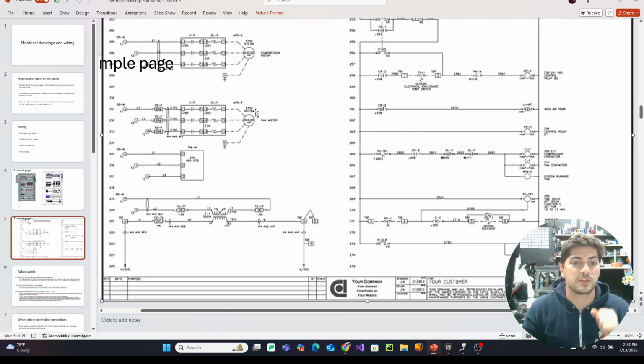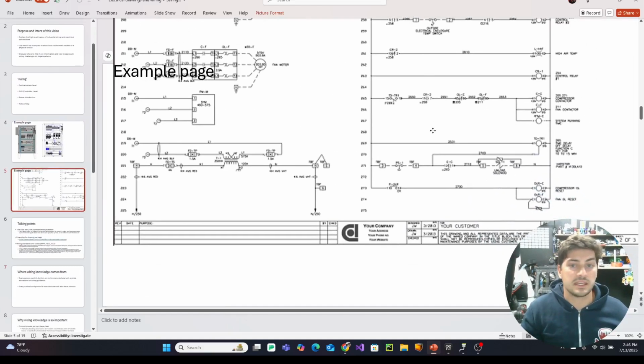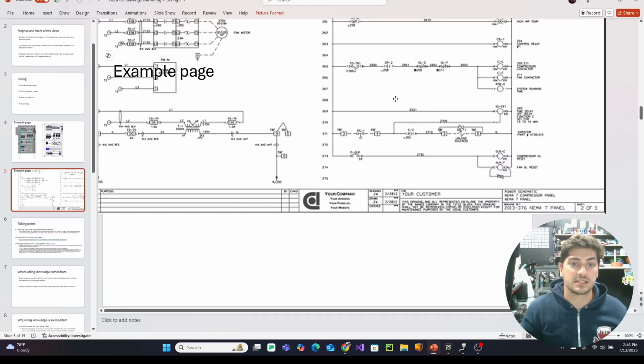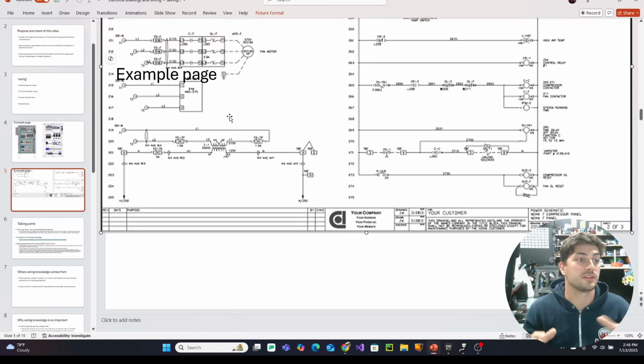And then the footer is actually where I want to spend some time here because the footer of the drawing package contains an enormous amount of information. Usually on the left side, you have revision notes, which would be the person who approved a revision, the date it got changed, which revision number or letter it is, and then usually a brief note or comment about the revision itself, like what are you adding, what are you deleting, what are you changing. It's very normal to see the latest revision or the newest revision have all the changes in like a cloud or a bubble format on your drawing.